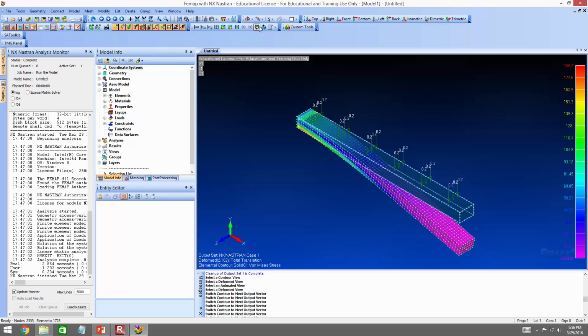You're going to take a benchmark problem to figure out how dense your mesh needs to be in order to attack the complicated problem. So you'll analyze something simple, something that you know, to confirm that your modeling technique is correct, and then use that technique to analyze something that is complicated. It's a standard process in finite elements: benchmark your analysis against a known result, and then use that same technique to analyze something you don't know. I'll work with you all to make that happen.